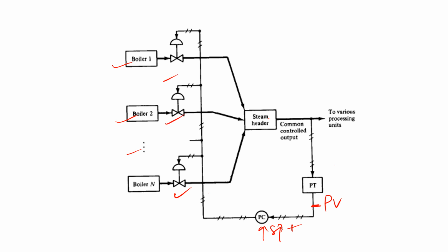Okay, so that's all for today. We have learned the cascade controller and the split range controller. Even in the split range controller, we have the normal conventional controllers only: P, PI, PD, PID. Because this is a pressure process, we are okay with a pressure controller. Even if there is an offset, we can increase the gain again to reduce the offset. So this is how your split range works.